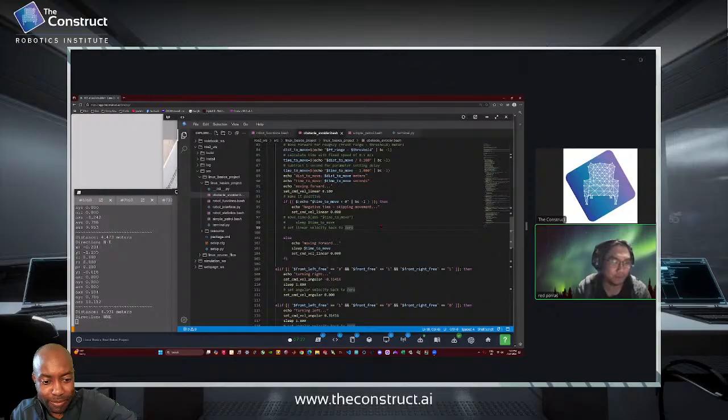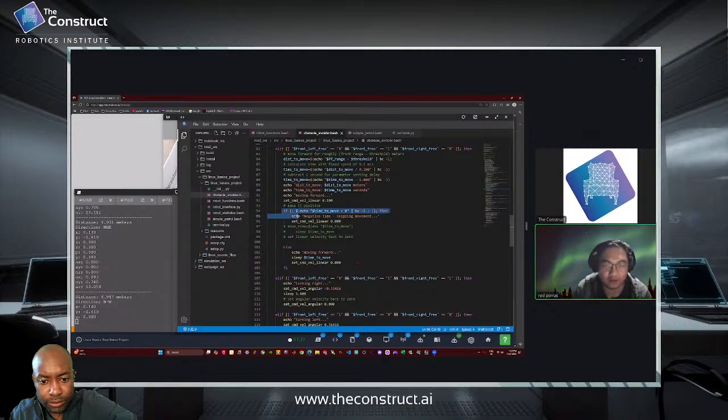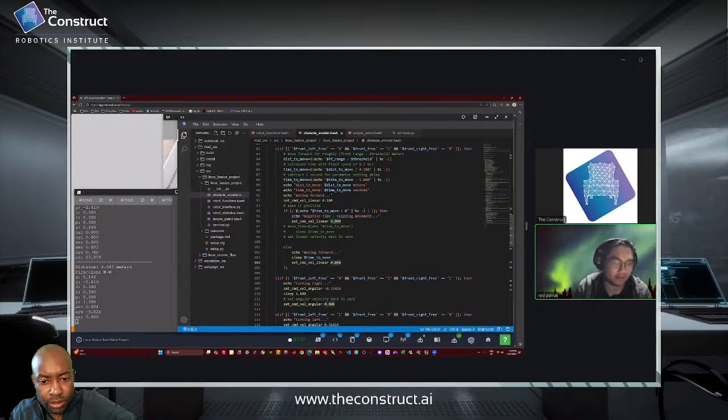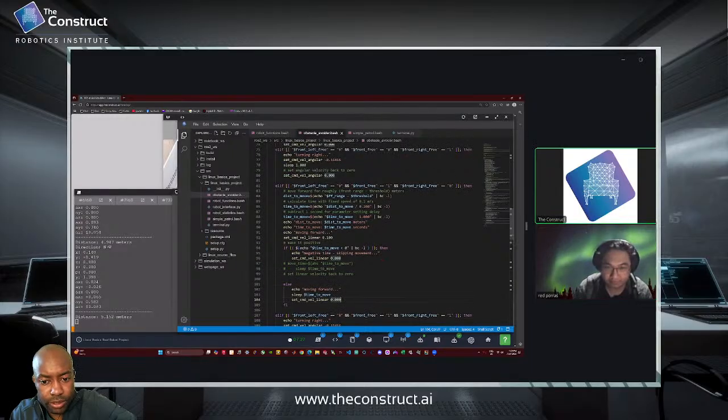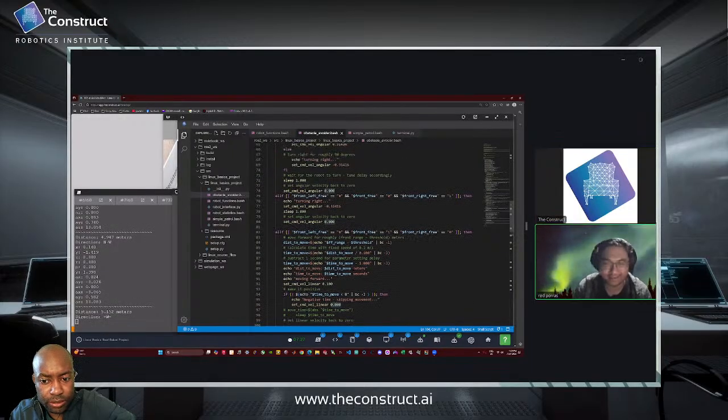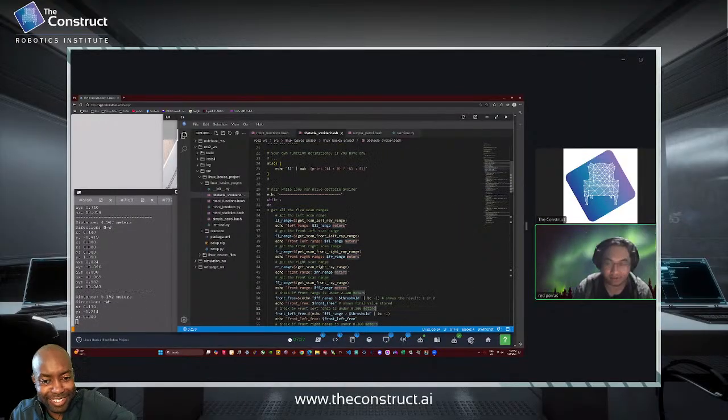But when I put that in, it made more errors, because the robot is supposed to stop when it's negative, but the function makes it move forward. So in Gazebo it goes out of bounds, and that terminated everything. So I removed it and changed it to an if-else statement: if it's negative, don't do anything, just stop; else, just go forward. That's what I did for that part, and it seems to be all working, so I'm happy with that.